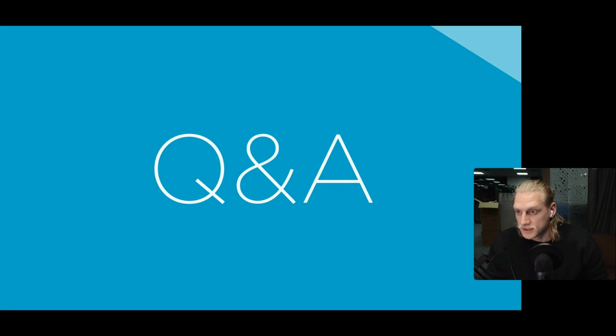Then I can't see any more unique questions. There is a comment about more algorithms being much better than coulomb counters. Yes, then we agree. Algorithm-based fuel gauging is better than coulomb counting, and algorithm-based fuel gauging is best when you get the hardware for free in your PMIC, and you don't need an additional processor to do the processing for that algorithm. You can just use the main system processor for it.